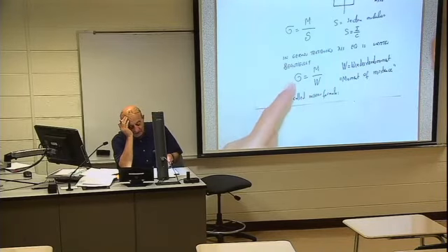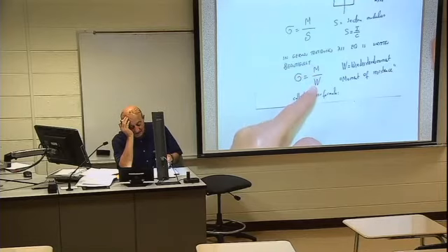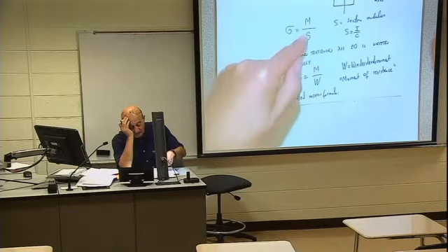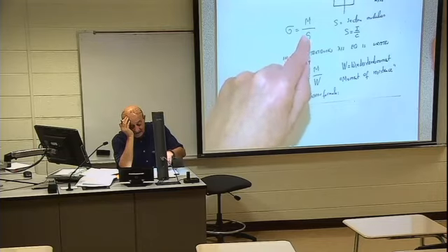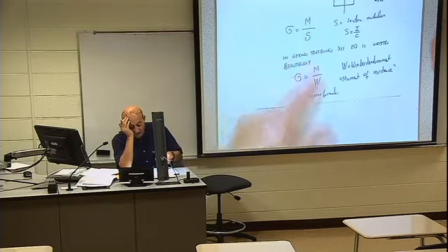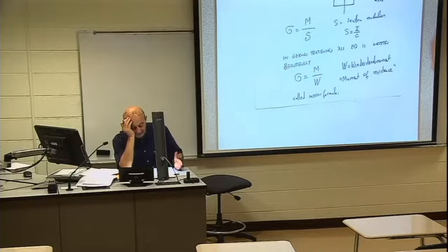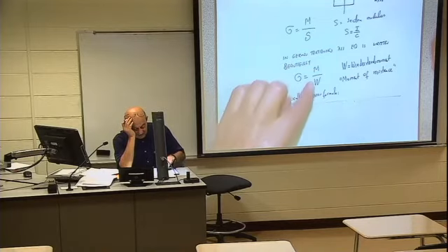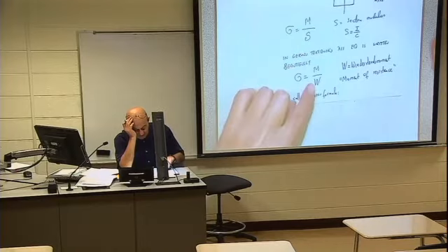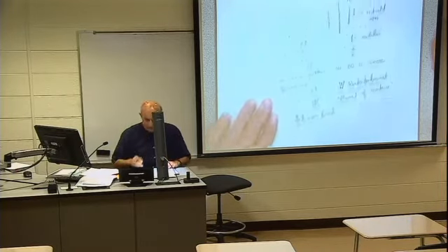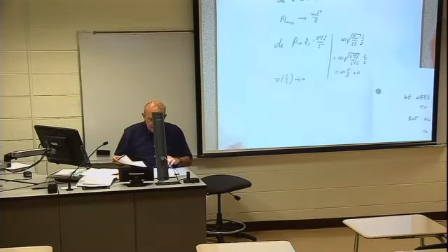So then what you have to remember is moment divided by W. Then instead of W, in American or Anglo-Saxon textbooks, it appears as section modulus, and it is not called moment of resistance. Resistance in German is Widerstand. Okay, therefore they denote it as W. Okay.